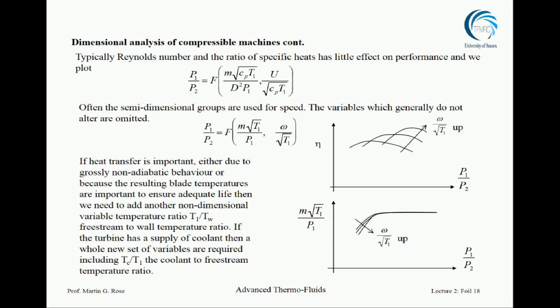And we have a fundamental problem inside a gas turbine because a gas turbine is a compressor coupled to a turbine. Turbines like going fast, compressors like going slow, and they're coupled together. So always the turbine engineer celebrates when we learn that the shaft rotational speed in the engine has gone up, because we'll be getting better, and the compressors are getting worse. And the compressor engineers celebrate when the shaft slows down, because they're going to be higher efficiency and we're going to be worse. And that battle is intrinsic in the gas turbine industry between two different camps of people. So yes, if you go faster, you get higher efficiency in a turbine, not in a compressor.